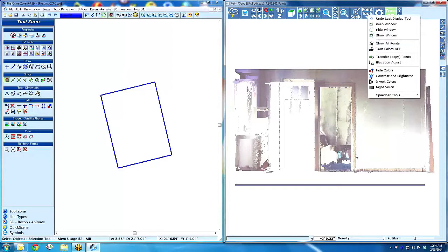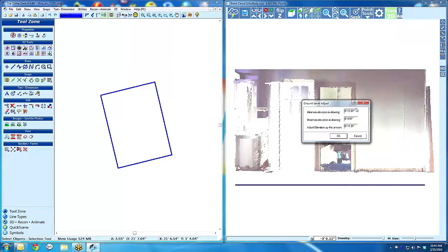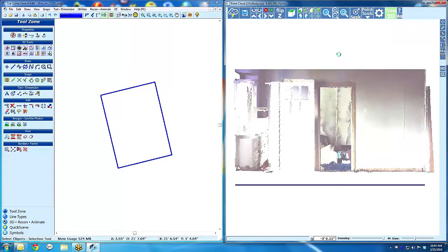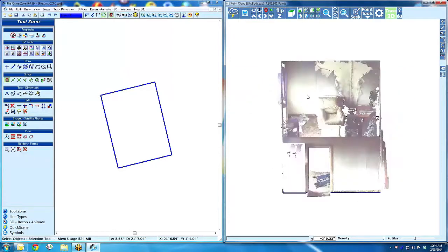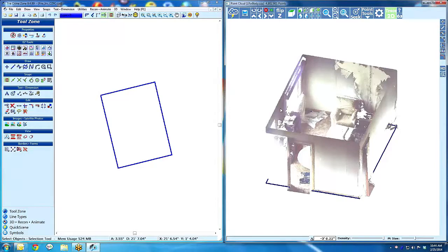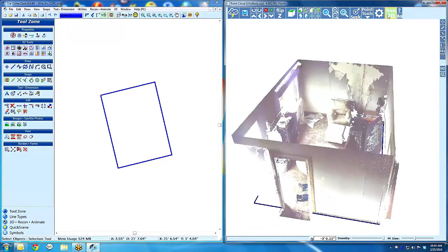So what I'm doing is I'm going to go back. What I did is I cleaned up the stuff underneath, and I'm going to do an elevation adjust. You'll watch this elevation adjust. It'll take a second to go through and process. It'll drop the whole thing down like that. So now, instead of trying to draw out in 3D, and we can do that, by the way, I could turn off this 2D trace mode and grab a line.